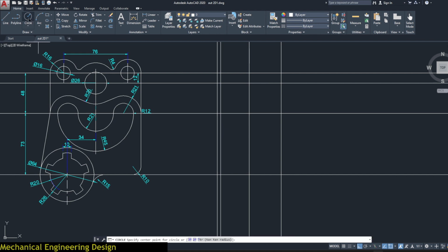Shall pick circle. Begin with this circle. We have a circle at diameter 64, and here is our center. Now by default, circle uses radius. So for you to use diameter, you can quickly switch here to diameter, and then type 64 like that. So I want us to quickly draw the circles on each center. Now enter. The second circle is on this point, radius of 21.